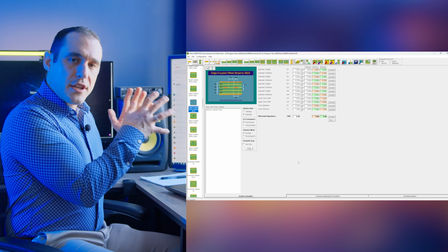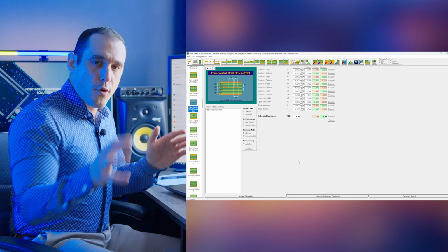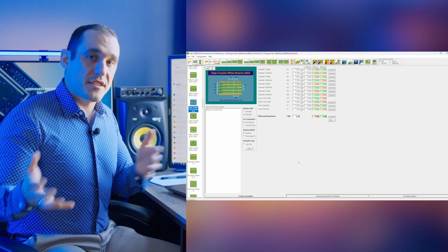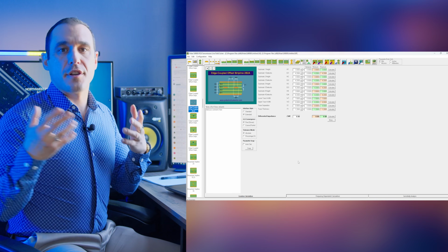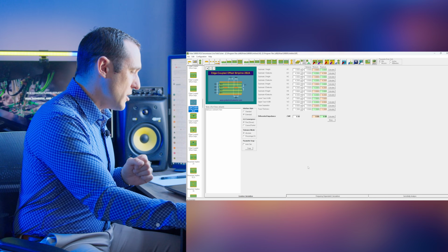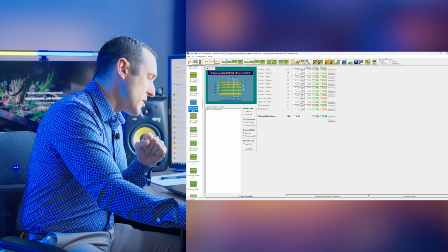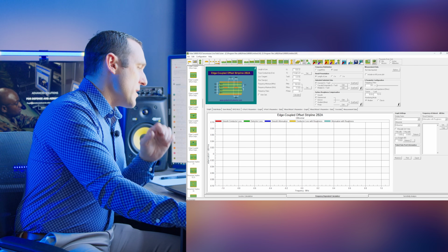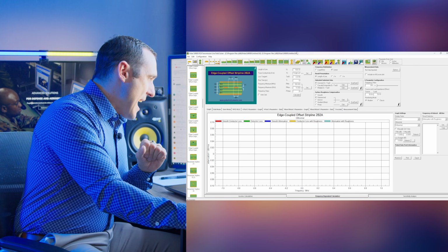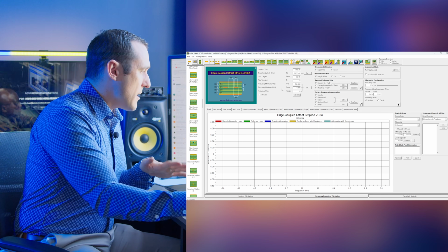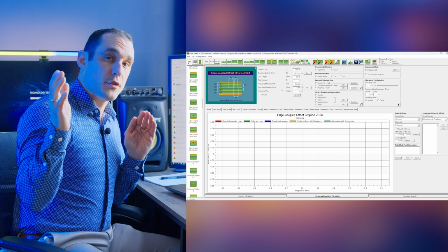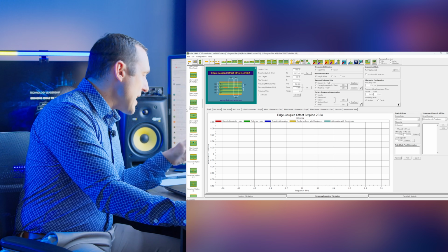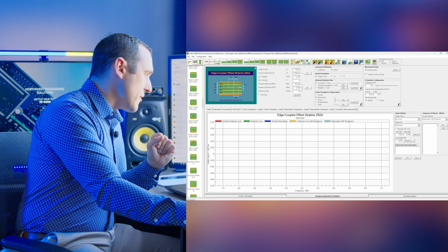Now here we're only looking at the lossless impedance, but of course all designs that have signal integrity considerations will experience some loss, and so that's why you need a frequency-dependent calculation. And that's what you'll find on this tab. So in this tab, you can do a frequency-dependent calculation as a function of your line length using any of those models that we saw on the previous screen.